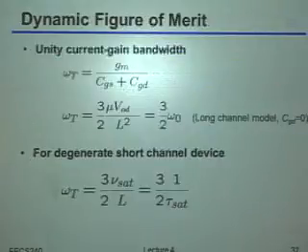Unless there are more questions on that, let's move forward and start talking about something that I think most of you are already familiar with. We spent a lot of time talking about what the capacitors are, but at the end of the day, it is typically easier to think about a figure of merit. For most of the designs that we will be doing, the figure of merit you're going to care most about is the so-called unity current gain bandwidth, omega t, or similarly ft, and the two are of course related by a factor of 2 pi.